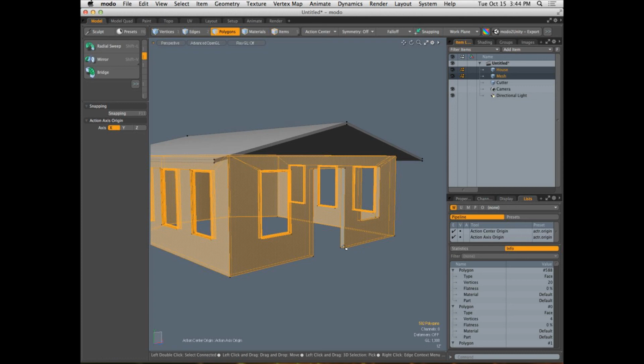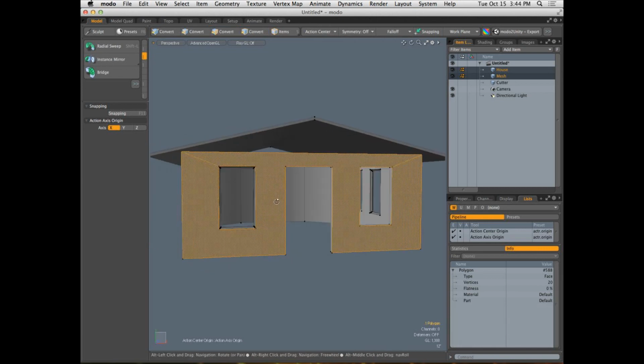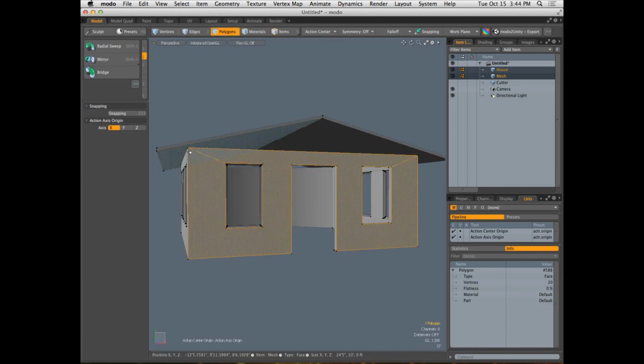Okay, this is actually bad construction geometry for most 3D applications because we did all those Booleans. Every single wall is defined by more than 4 vertices. Like this one right here is defined by 1, 2, 3, 4, 5, 6, 7, 8, 9, 10, 11, 12, 13, 14, 15, 16. This is a 16-sided surface. Okay, this is bad geometry. So the loop slice didn't work because it doesn't understand how to slice it. So that's out.